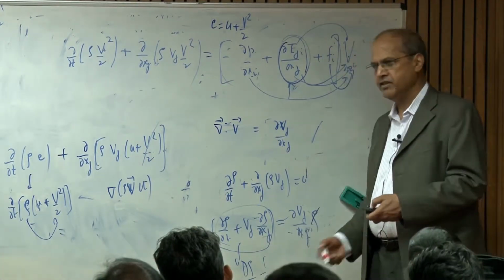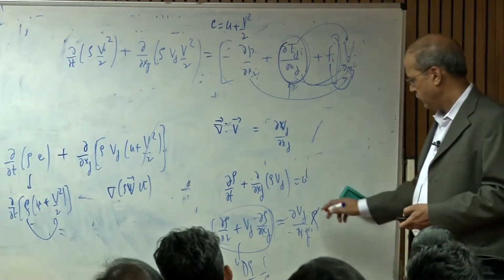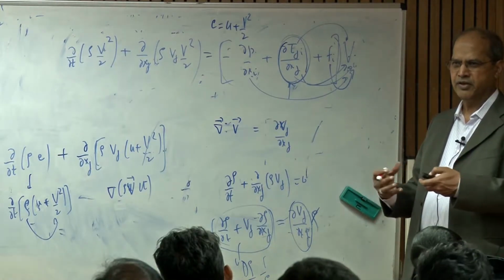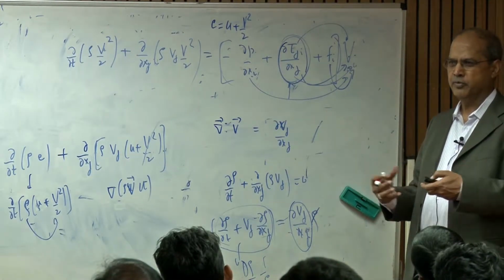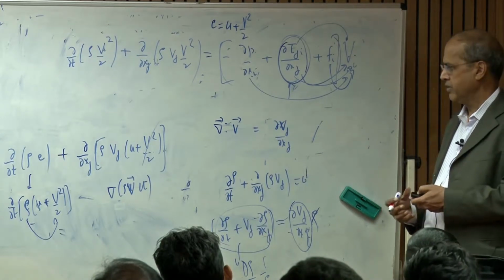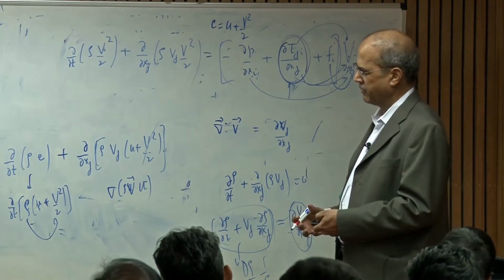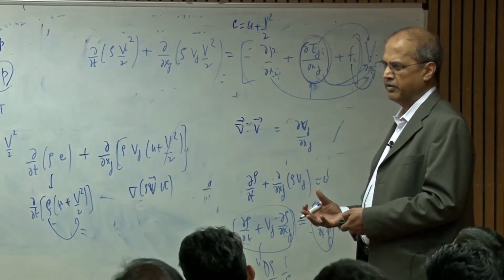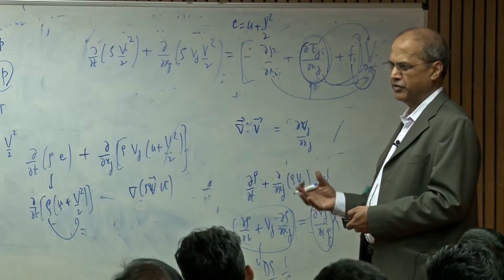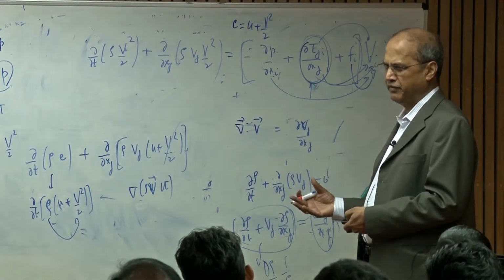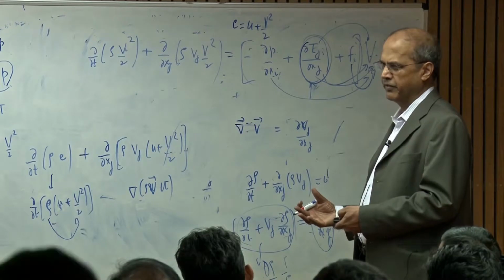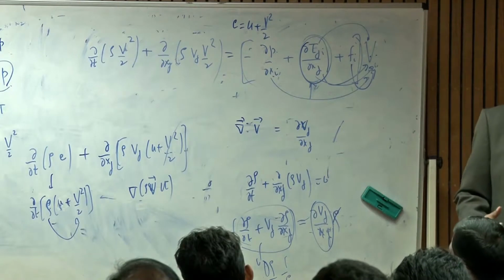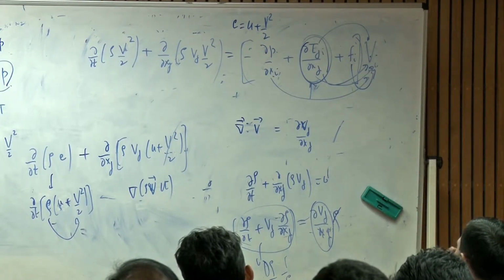If the density decreases, then the volume will increase. So you see, this term represents the rate of change of volume of the fluid particle. So now come back here. This is what we call PdV work. Remember, we just write change in energy is delta Q minus delta W, which is PdV. So this is the PdV work, because divergence of velocity represents the rate of change of volume per unit volume. It's like the percentage rate of change.